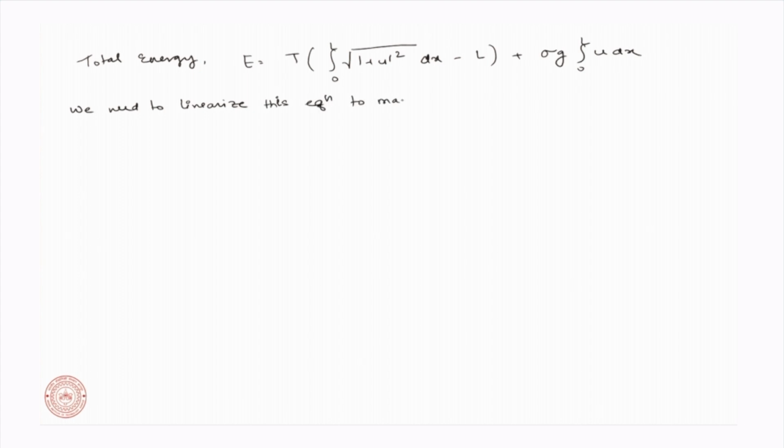To match with our Navier's equation, that is a small strain approximation. Okay. So, we have linearized our Navier's equation based upon the small strain assumption. That is, we could have taken the Lagrange strain or the Eulerian strain, which had this square term.